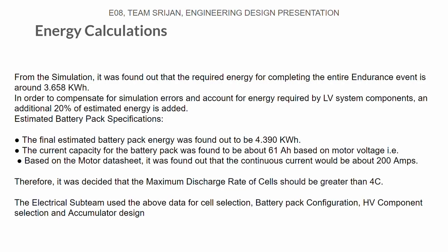From the simulations, the total energy required to complete the entire endurance event came out to be 3.658 kilowatt hour. In order to compensate for simulation errors and account for energy required by the LV system components, we add an additional 20% of the estimated energy to the result. The final estimated battery pack energy came out to be 4.39 kilowatt hour.